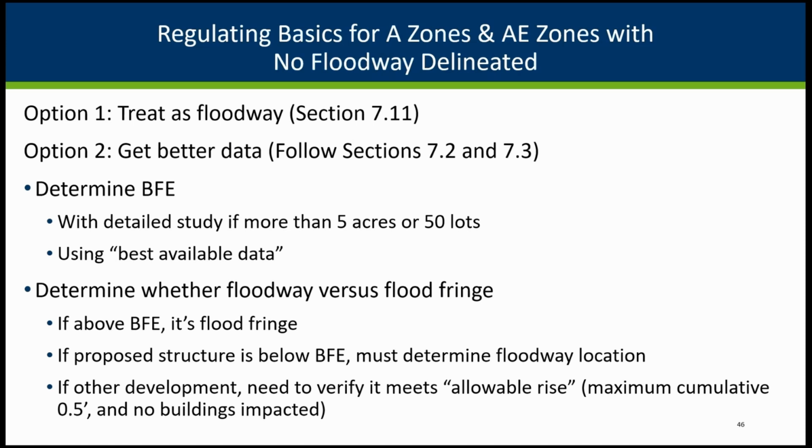So if the mapped area is above the BFE, it's treated as flood fringe. And if it's within the FEMA mapped area, you're still regulating it, but they're going to be allowed to put buildings there. They would still need to make sure they're meeting the minimum elevations, but it's an easier process. If it's below the BFE, you've got to figure out where that floodway location is.